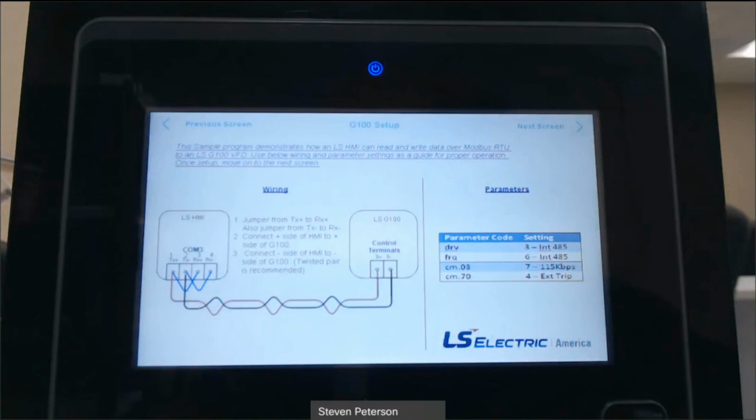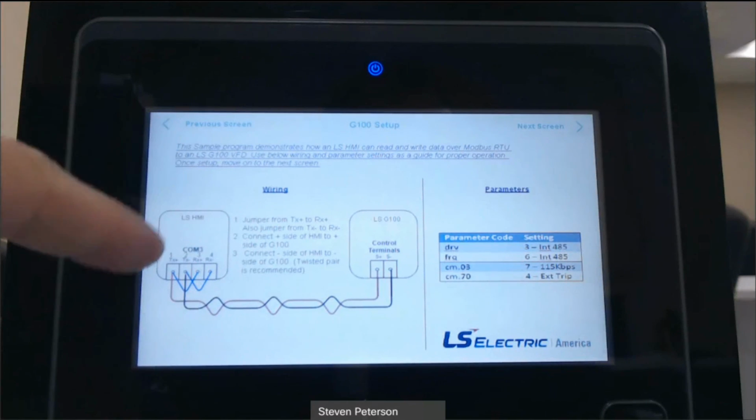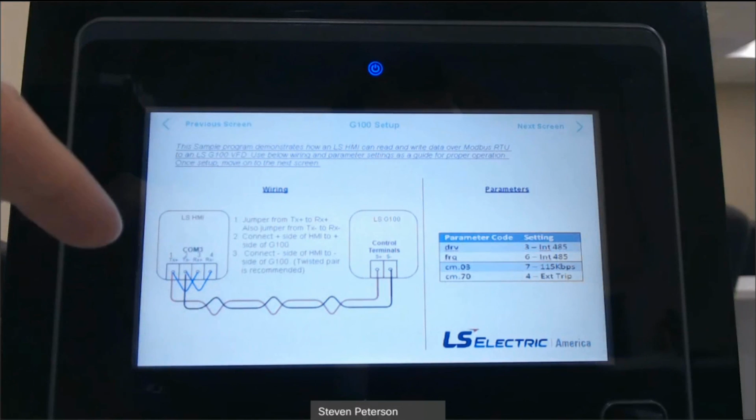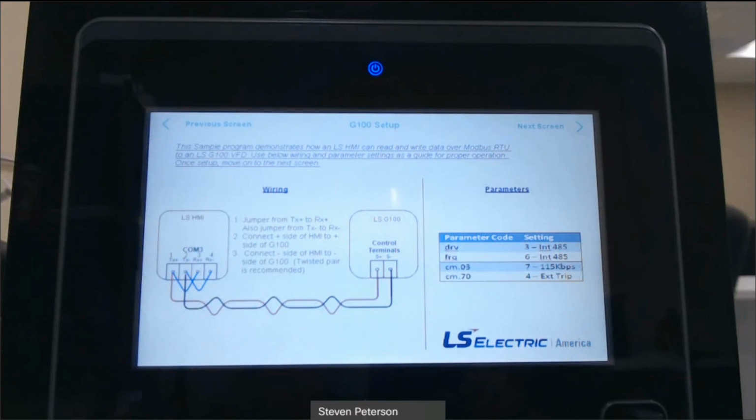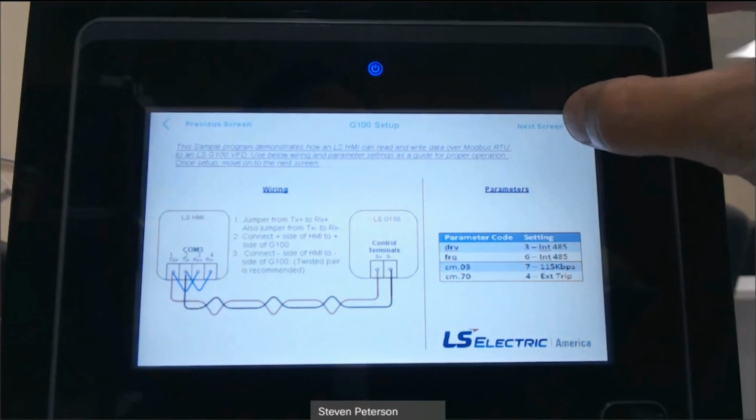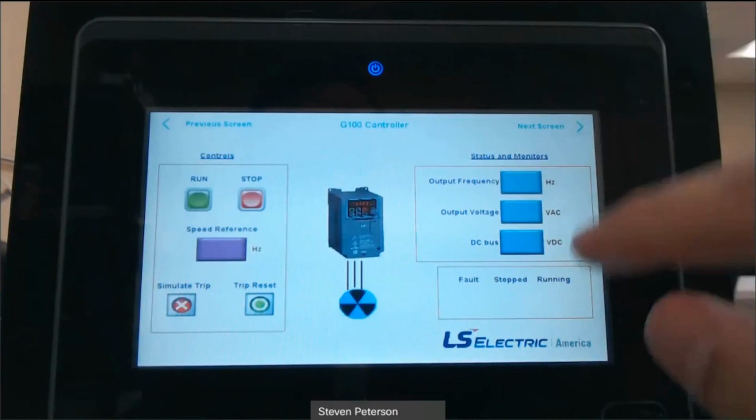So we fixed that. The last thing I'll show you real quick, just as a little trick to know, is let's say we get a PLC timeout. So I'm going to shut my drive off. If the drive's off, obviously we're going to lose communication because we can't communicate to a drive with no power. So in a few seconds, we should see a PLC timeout come up on the top. We'll give that just a moment. And then everything should be blank. Yeah, it's already acting slow. So nothing's popping up here.